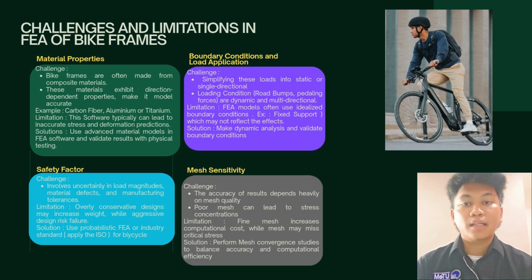Secondly, applying realistic boundary conditions. Bike loads are dynamic and multi-directional, from road bumps to pedaling force. FEA often simplifies this into static conditions, which don't truly reflect real world effects. Dynamic analysis is crucial, with careful validation of boundary conditions. Second, safety factor and mesh sensitivity.